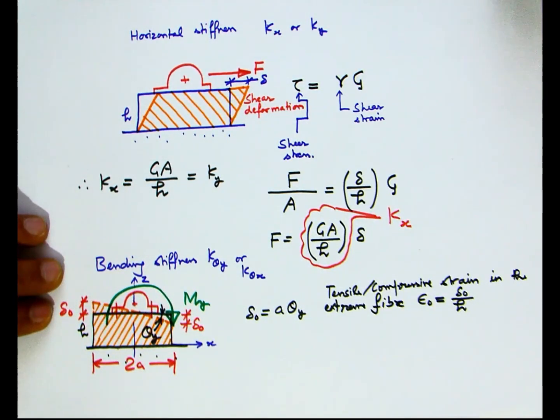We begin with writing the expression for the tensile or the compressive strain at the extreme fiber. Then we express strain in terms of the stress and the Young's modulus.